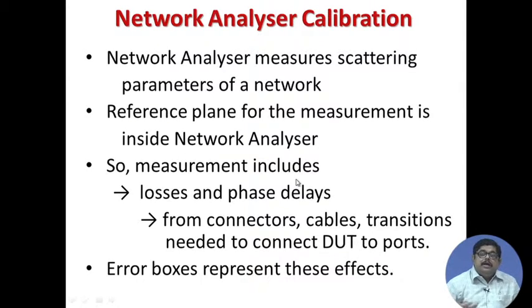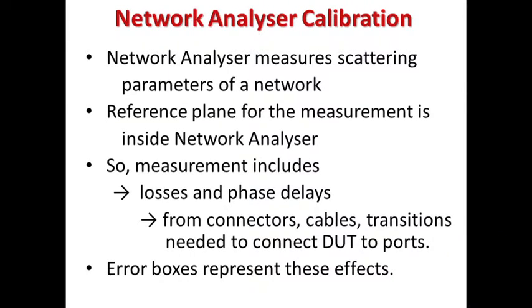Now, as the network analyzer is a very precise measurement, these errors become significant. In a microwave bench, etc., the measurement itself is not so precise. That is why there, even the errors caused by the change in reference plane do not come into such prominence, but here in the network analyzer, since it is a very precise instrument, this needs to be corrected.